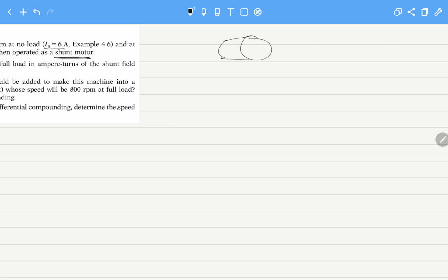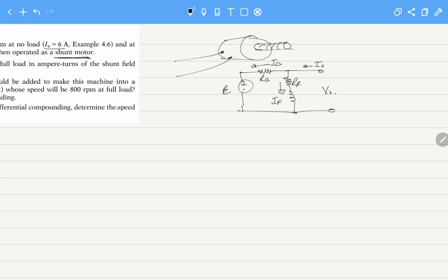Now for a machine, for example a DC machine, we want to control its speed. So for a shunt motor, this is the typical characteristic. We have a terminal voltage Vt, and a current It flowing from the DC source. It flows as If and as Ia. This is Rf, this is Ra, and this is the internally induced voltage Ea.